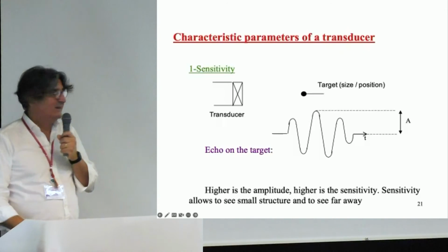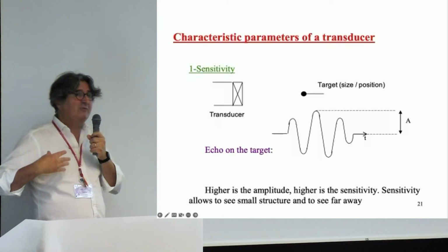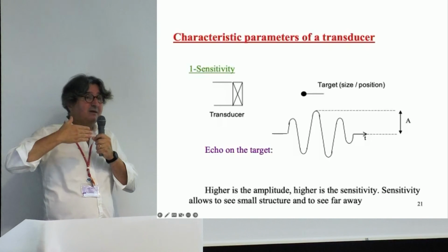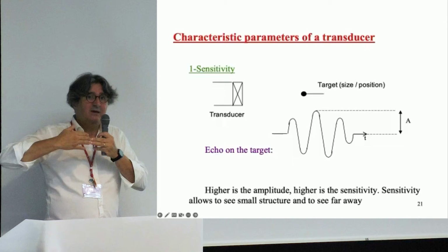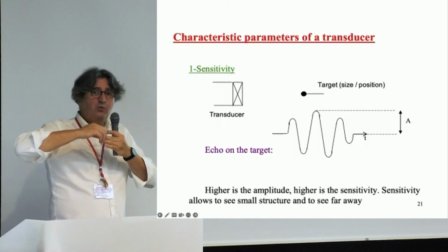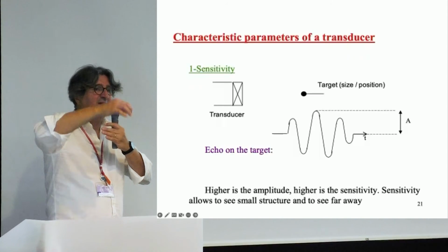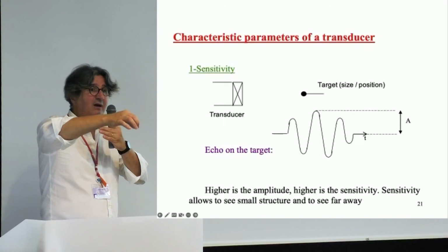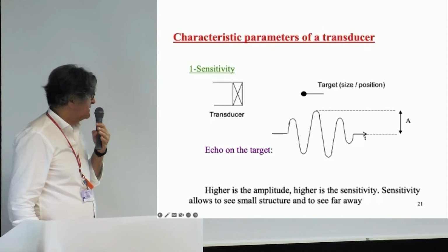So that's one point. And for instance, if you are doing inspection in metals, having a sensitive transducer is very interesting if you have big pieces, because you will be able to observe defects at a very large penetration depth. That's the idea.